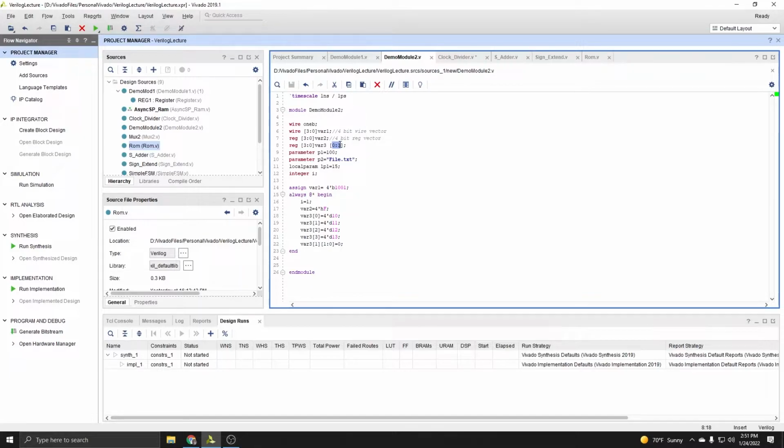Basically you'll be declaring this similar to how arrays work in a language like C, where arrays start at 0 and increase in index. So you'll always be making these arrays with 0 to whatever the limit that you want is. And similar to the vector sizing, keep in mind that that 0 is included in the amount, so your upper limit will basically be your size minus 1. But that's really it for the main two. Those are all what you'll be using in your actual logic of your modules.